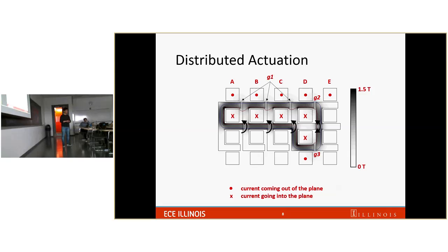Would it be possible to use an optical encoder or Hall effect sensor or something? It seems like there are other options. With a potentiometer, you'll always have to be pushing current through it and losing power to read your position. So I'm just wondering if there's a lower power way of doing it. Well, I'm using low power, because the potentiometer is connected to 3.3 volts, and the whole resistance is 10K, so the current is really small. Okay. And the reason why I chose the potentiometer is that it's really small and cheap, so I can easily mount it on the system.